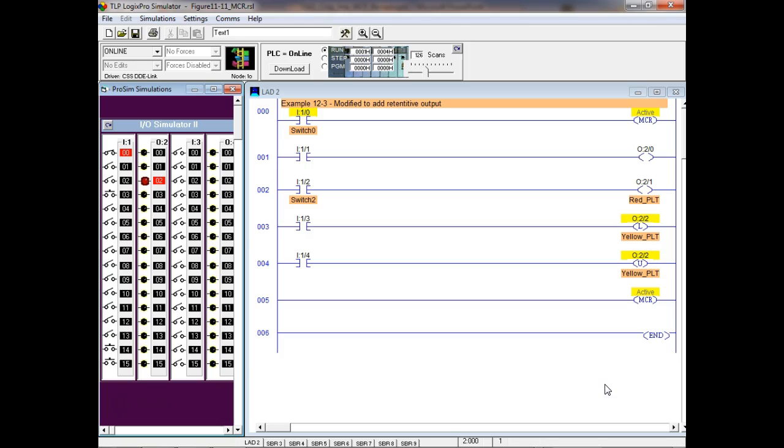Now, how do I turn that thing off? I'm going to hit switch 4. These are momentary. And then it unlatched. So this does what to it? Latches it. And this does what? Unlatches it. Why does it highlight the other? It's the same. Yeah, because it's technically the same relay. If I looked at my big relay over here, I've got two sets of coils, one called latch and one called unlatch, but it's controlling the same outputs, right?